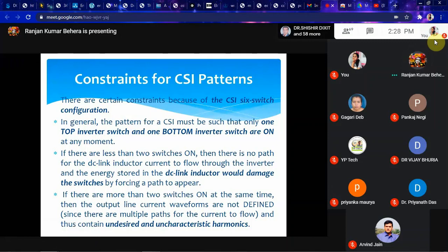For example, for a square wave, we get the fundamental, then third, fifth, all odd harmonics. When you have a quasi-square wave, you will have absence of the third and multiples of 3 harmonics, but you will have 5th, 7th, and so on. If fractional harmonics like 1.5 come, you cannot define those things. So that is why it is very important.